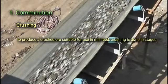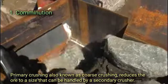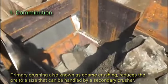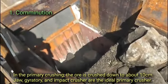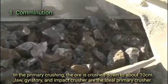They are primary crushing, secondary crushing, and tertiary crushing. Primary crushing, also known as coarse crushing, reduces the ore to a size that can be handled by a secondary crusher. In the primary crushing, the ore is crushed down to about 10 centimeters. Jaw, gyratory, and impact crusher are the ideal primary crusher.